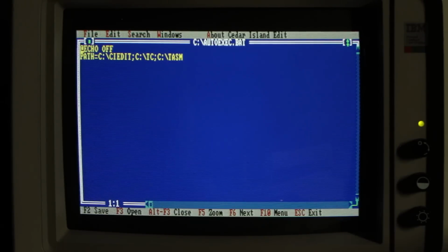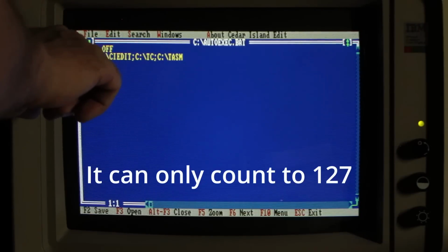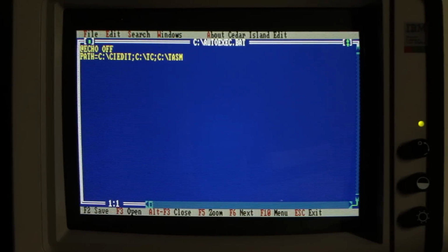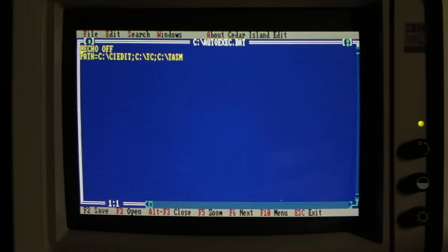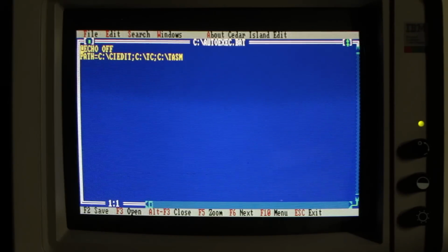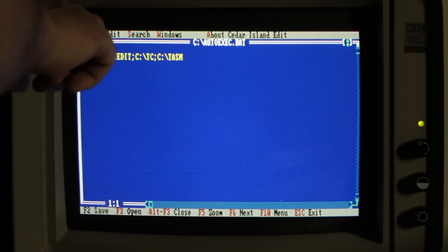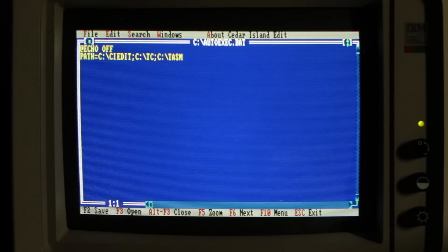So you get unique information for each scan line on the screen. Unfortunately, a little limitation of the CRT controller chip made it impossible to do that. So they actually had to use 2 scan lines per character row in graphics mode. So you actually have 100 characters down the screen, each of which is 2 scan lines high in graphics mode. And in order to not duplicate the same pixel information for each of the 2 scan lines of a character row, what they do is they use the row address, which is now alternating 0, 1, 0, 1, 0, 1 all the way down the screen.